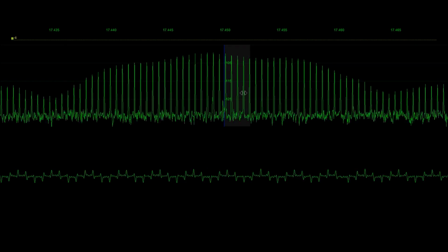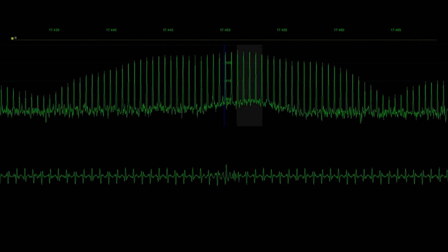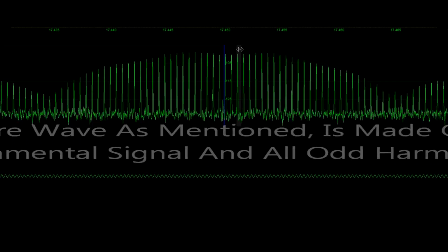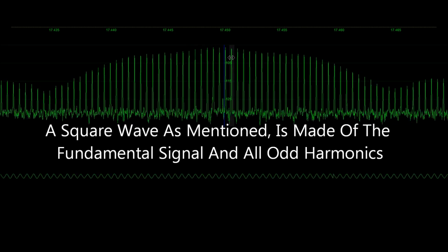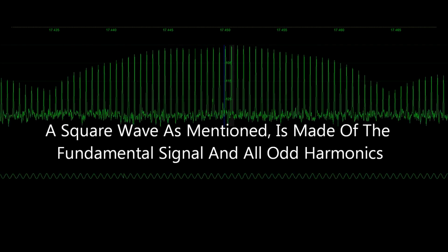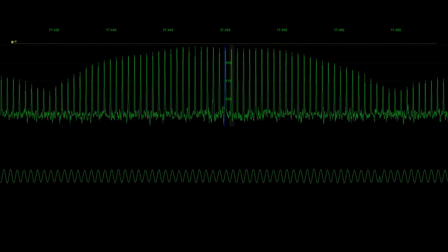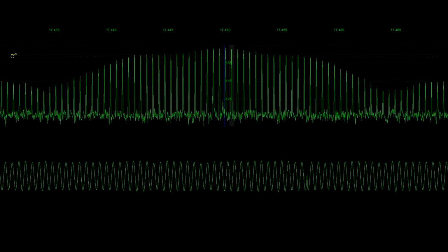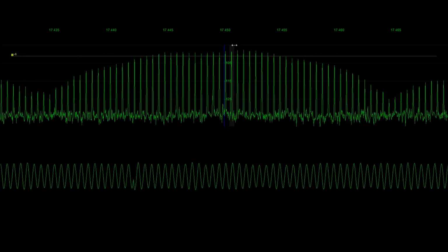Okay, let's start to zoom in, and let's start to isolate one independent carrier now. Okay, we'll go pretty narrow there. Alright, this one is approximately 630 cycles above the center of the receiver. I'm going to put some gain into the receiver now so that we can look at it on the scope. Okay, now you can start to see that this is a sine wave, this particular format.